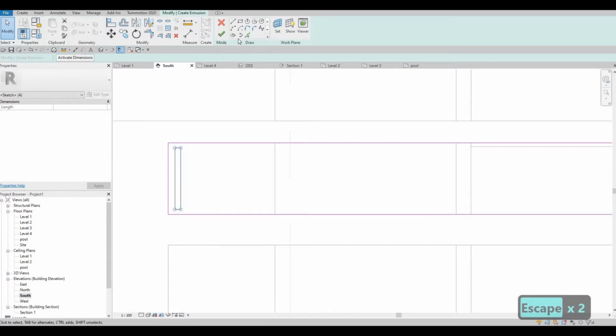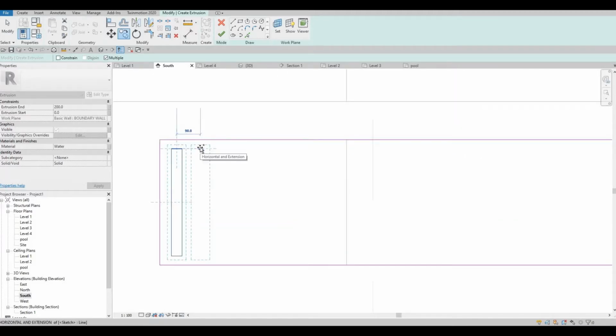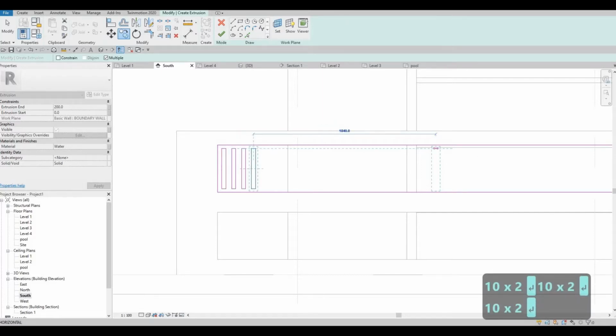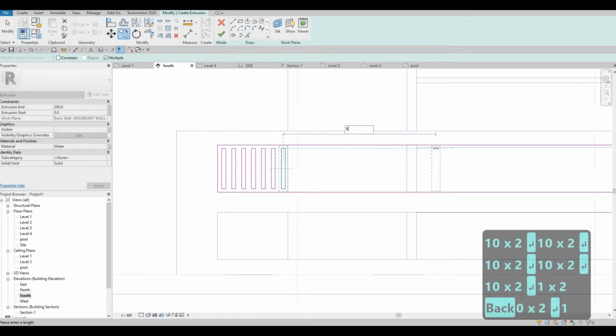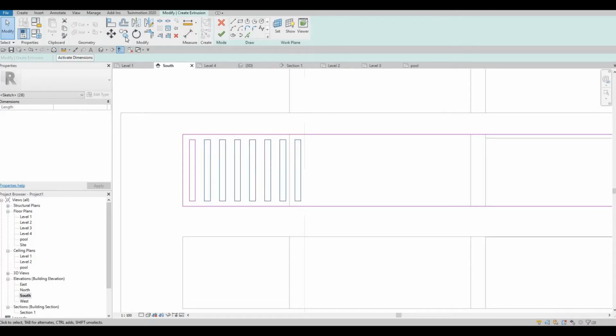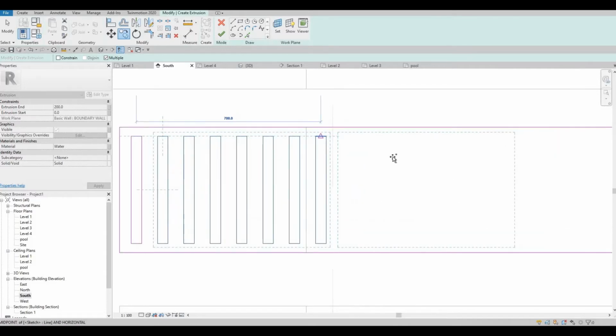copied and has holes. So we're gonna copy this multiple times, make sure this is multiple, and then type in 100. So just keep on typing 100, and once you have enough, you can select all of them except for one, and then copy again, and then grab it from the midpoint there.